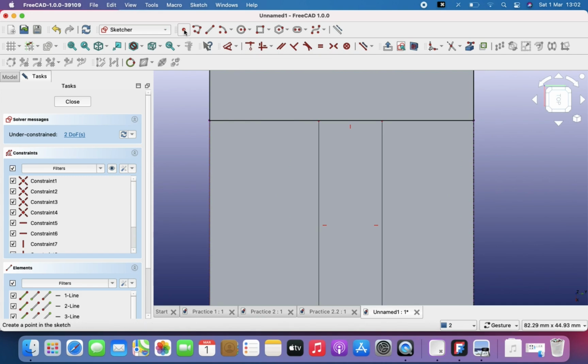I'm going to click on the points tool here, and if you see, I'm dragging my cursor along the line of the rectangle, and the constraints showing will change depending on where it is on the line. Right now it's showing me that if I put that point where I am, it will be on that line and will not be able to leave that line.